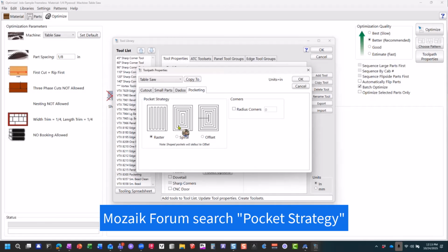Your machine has to be pretty good and trammed in order to do an MDF door. That's what that would apply to, an MDF door, but shaker or something. To give you an example, my buddy who's got the SCM, he bought it used and it had been crashed numerous times. We know that there's issues with the tramming on it. I've done some MDF doors for a personal project with this, and they actually came out pretty nice compared to the other options. So even with the machine being out slightly, it still did a nice job with that raster.